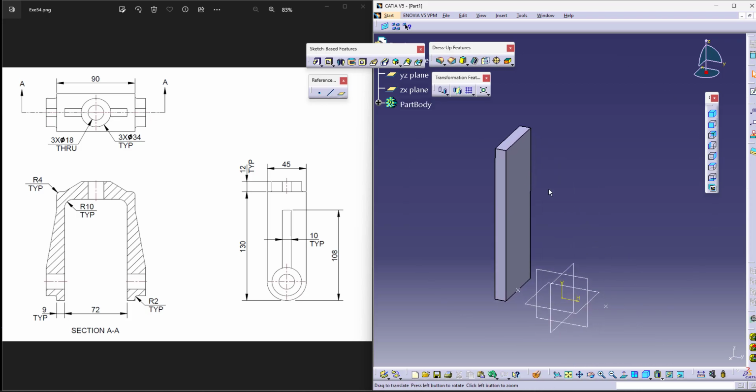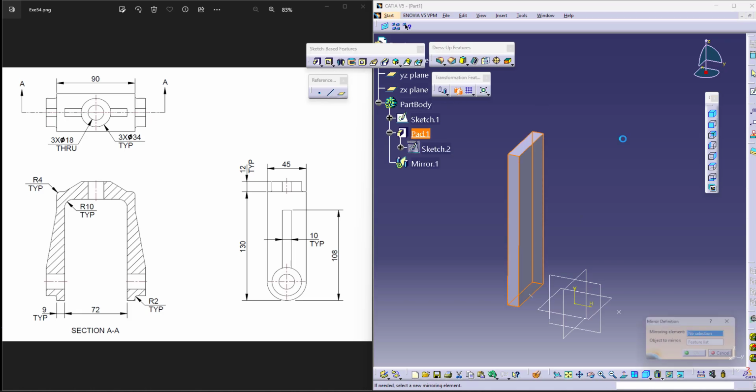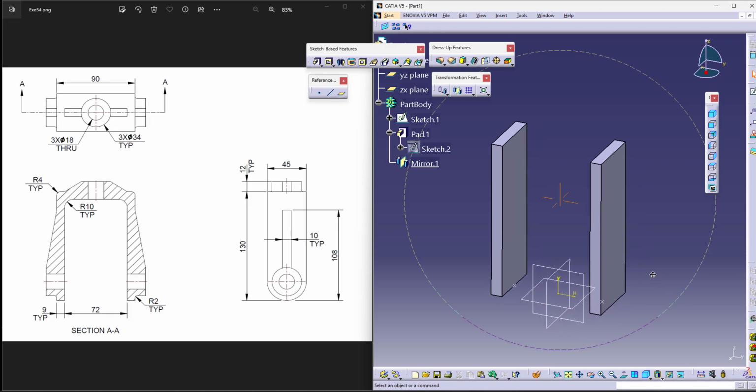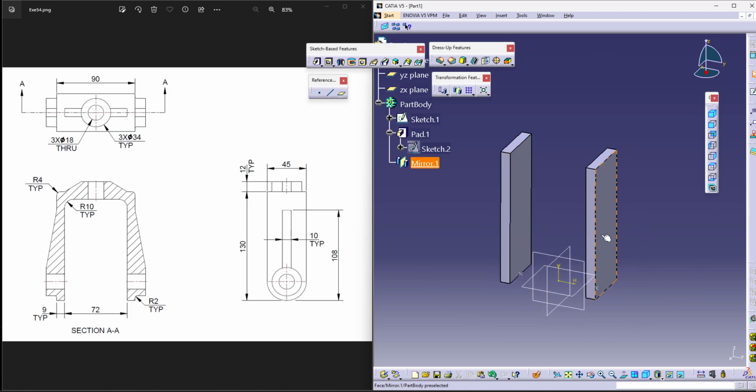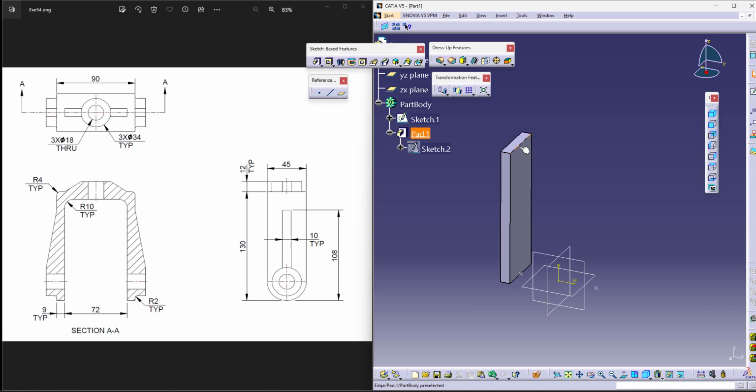Now, you should never mirror this feature. For instance, you can directly select this and do the mirror operation. A lot of people tend to do this. This is particularly not allowed in any tool test or in any 3D designing technique because it's one single component and one single component cannot have two bodies lying in the air. They cannot be detached from themselves. So instead what do we do is we create this top bar and then the other side.